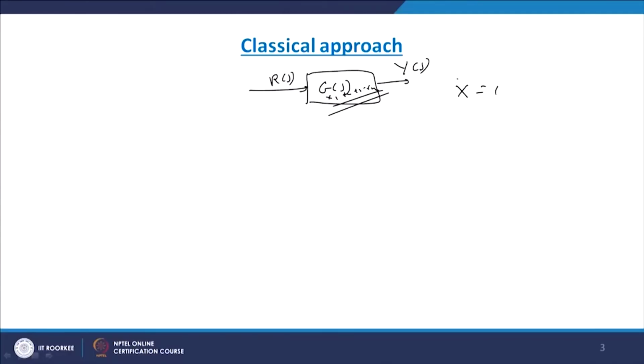Till now we have seen that we have to calculate the stability of the system and convert it into different forms, but along with this there is a need to know the state equation of the system. Now, how do we calculate the state equations? The plant which we have considered is x dot equal to Ax plus Bu, y equal to Cx plus Du.